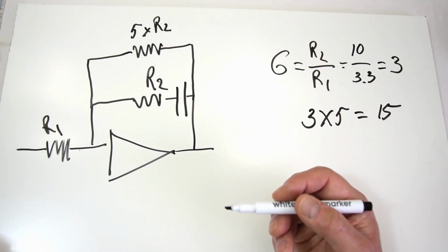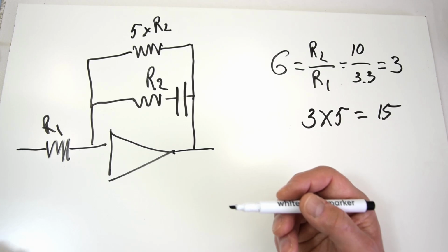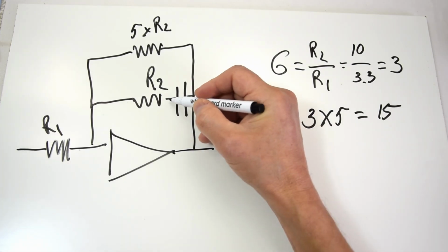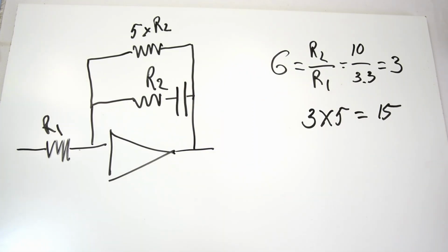So I think it would be nice if the tone control is adjustable. The way to do this is to add a variable resistor or a potentiometer. I think the way that it has the least impact on the volume overall is to place the variable resistor over the capacitor. So let's place this circuit on the breadboard and see how it turns out.